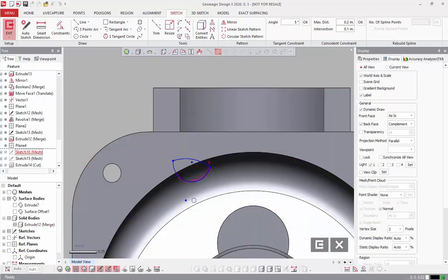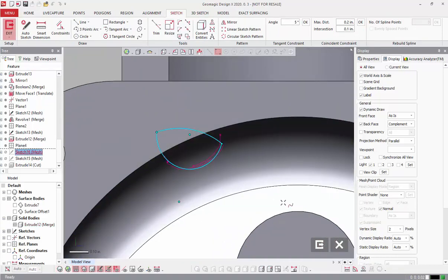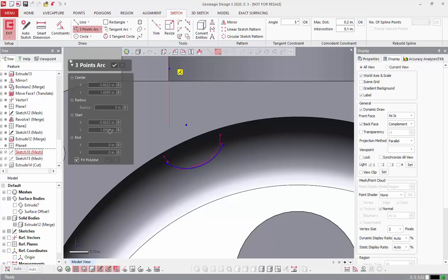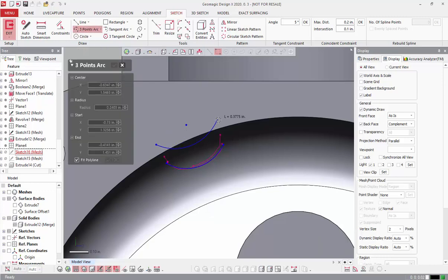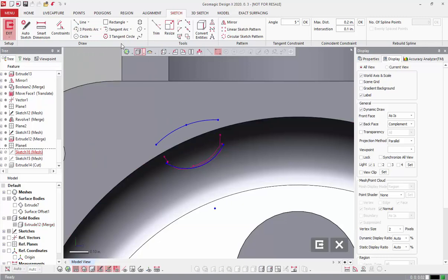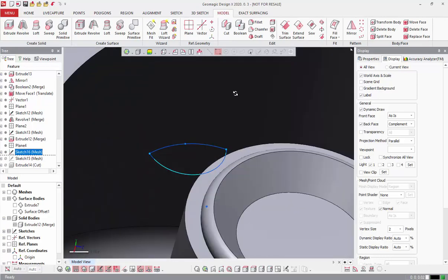So go ahead and go into the sketch mode here. What I really want to see is that feature there. I'm not sure where this plane lies, but if I can get the outside shape there and then just make sure we've got another circular feature that's within the body here, everything will trim together just fine. And where's that sketch? Somewhere towards the bottom.